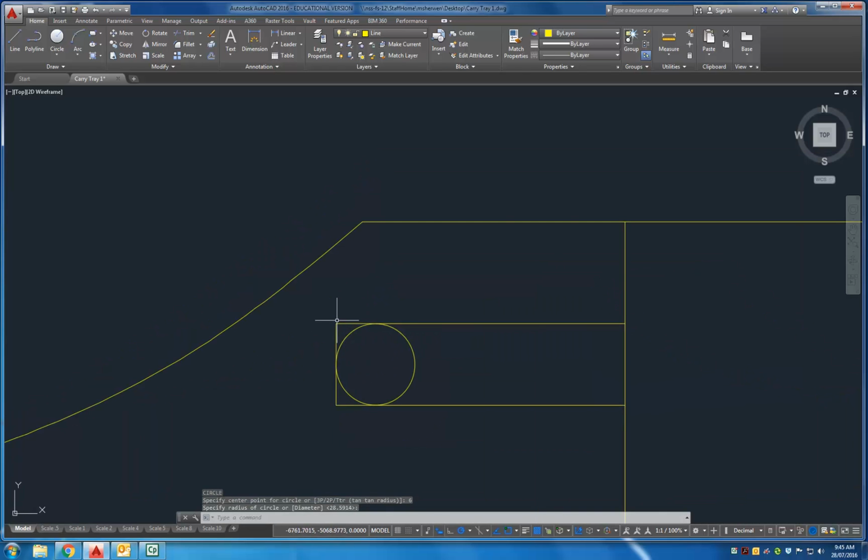Now I need to get rid of these excess lines. So to do this, if we click trim, so we start typing trim, TR, then make sure you press enter twice. Then we can trim any unnecessary lines. Trim, trim. Now this last one won't let us trim because it's not intersecting anything. So simply press escape a few times, click on the line, press delete.